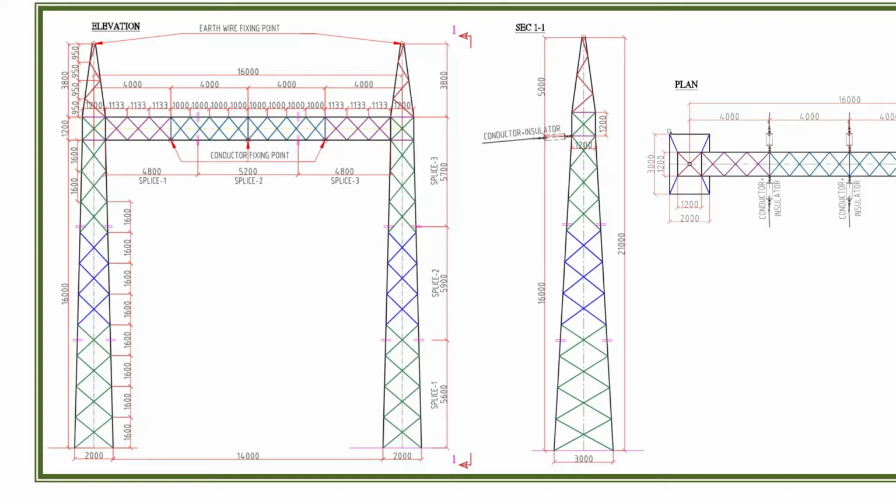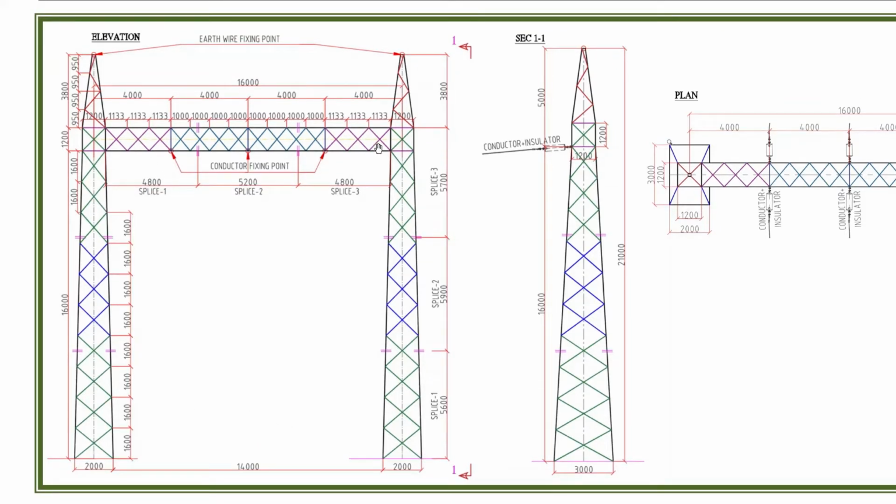So this grouping is very important to have a minimized output sequence, where we can identify which group falls under a specific load transfer system. Similarly, for the girder also there are two groups of cross bracings. One is in magenta color, another one is blue color. The first group, magenta, is nearby the tower, and the other one is mid span.